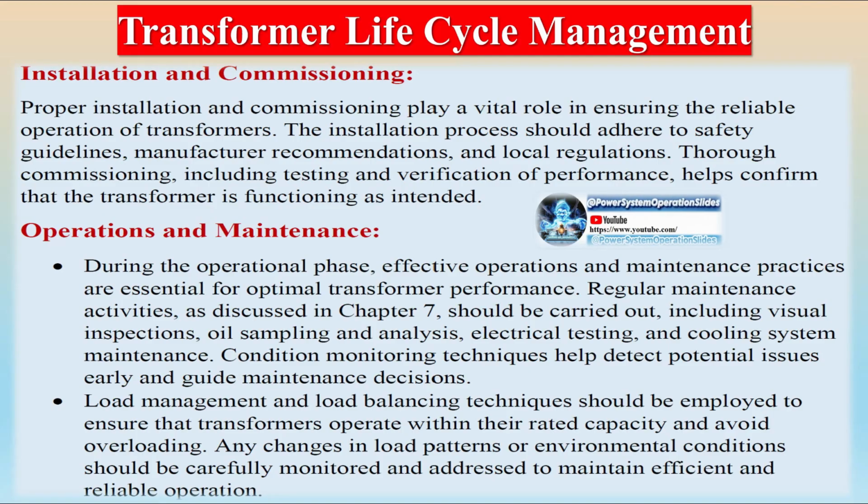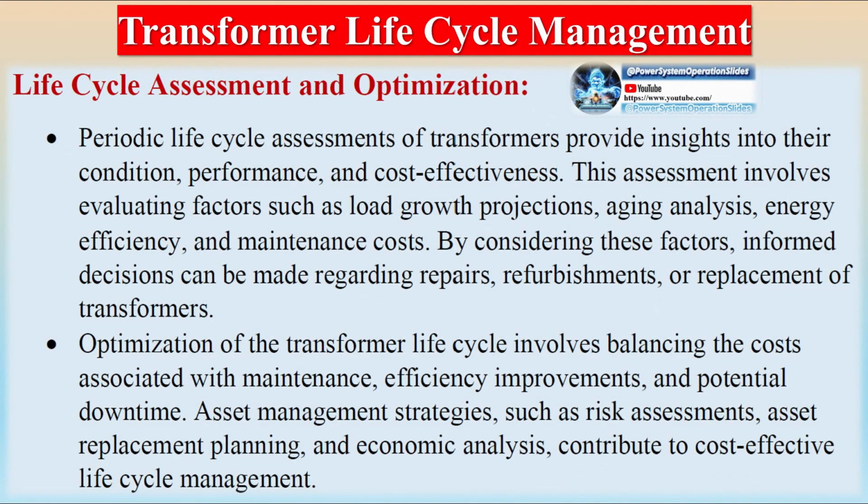Tap changers allow for voltage adjustments to accommodate variations in the supply voltage or load conditions. On-load tap changers (OLTC) enable voltage regulation while the transformer is energized, while off-circuit tap changers (OCTC) require the transformer to be de-energized for tap changes.